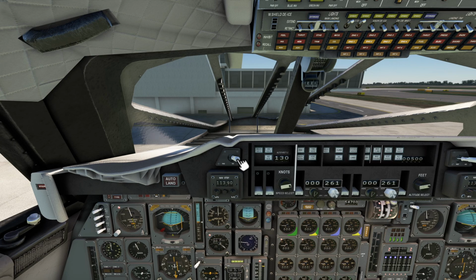If we approach our destination, we go back to RAD. That means the left side is going to come active, and we can choose our own ILS settings for the approach, which we're going to initiate by clicking on glide slope, or even land to autoland. But we're going to fly manually. For the moment, we go back to INS, so we're going to follow our flight plan.